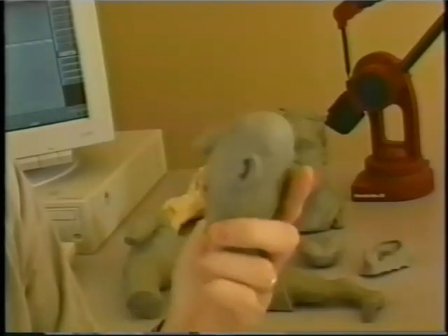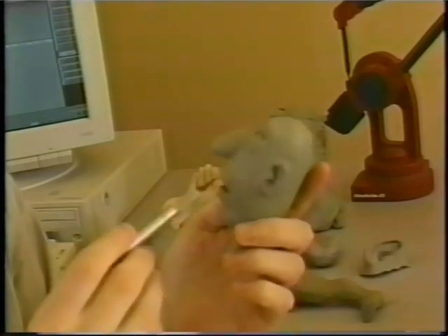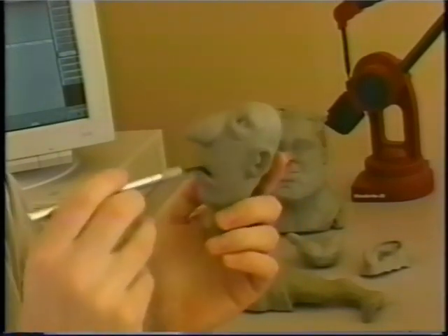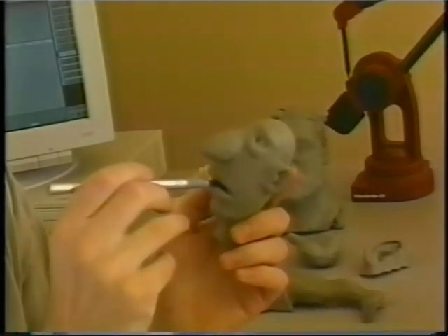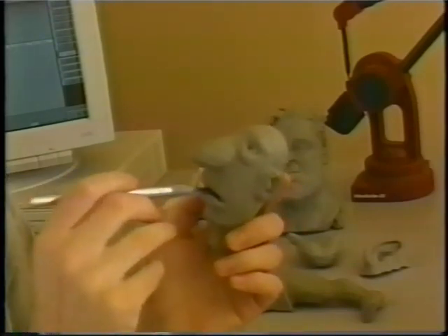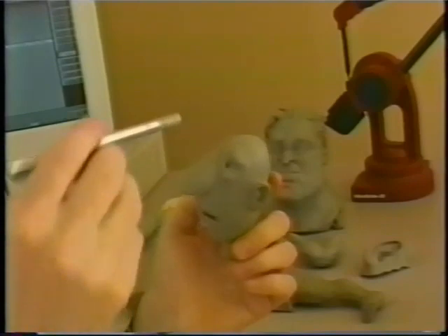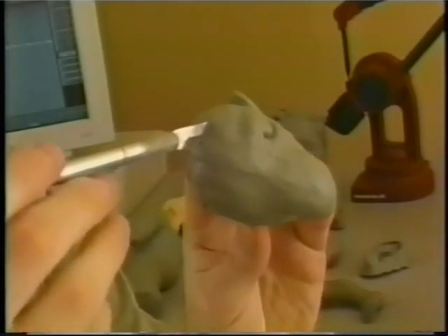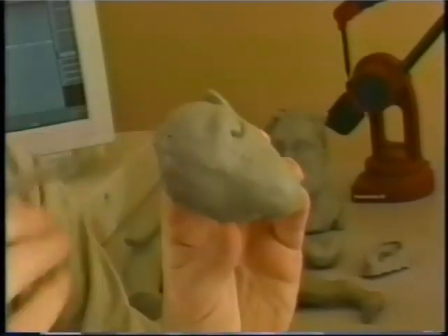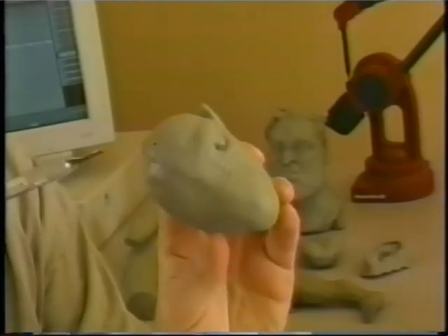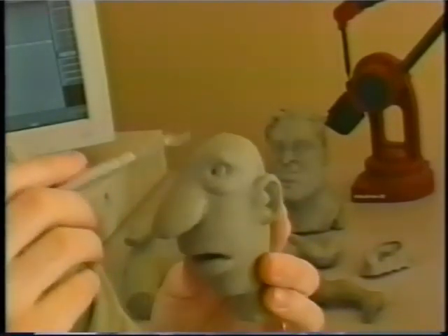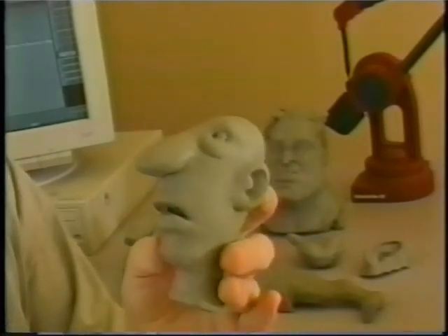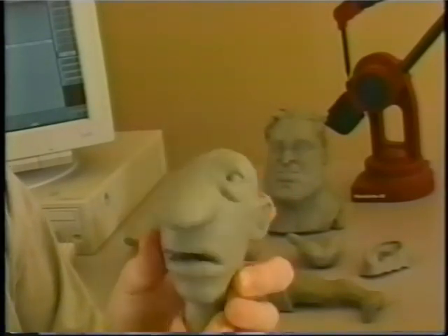Now heads, faces, they're one of the more difficult things to deal with. This cartoon character has basically a top to bottom layout, and so rather than going radially out from the mouth, having a pole in here, having one of those ends of the piece of paper coming in here and going out to the back or to the neck, start at the top. So you can see at the top there are lines coming to one point. All these lines coming up the head all converge in this one place. And that's the pole, or the one pole. The other pole is at the neck, and you can either stop here if it goes under a shirt or something like that, or you can continue on if it needs to be seamless with the body.